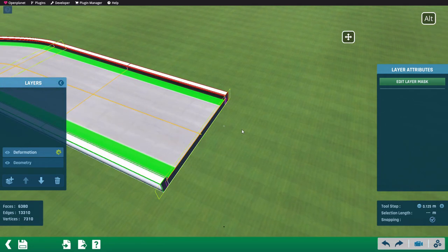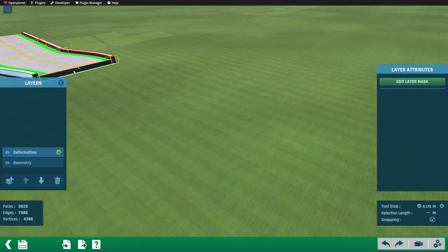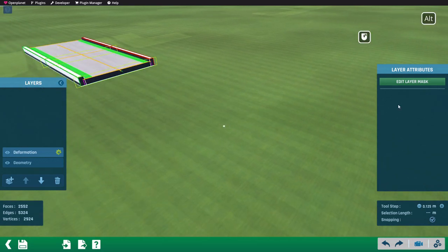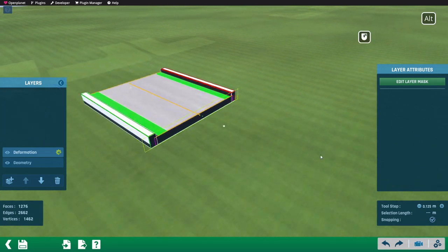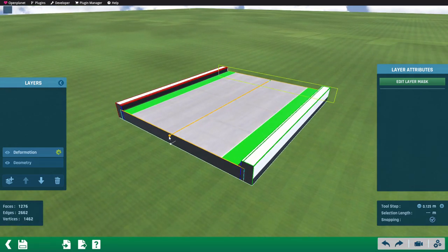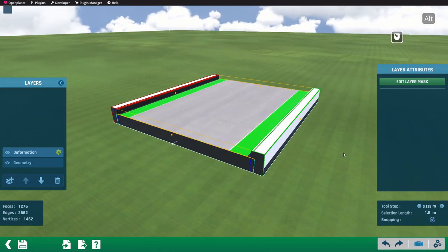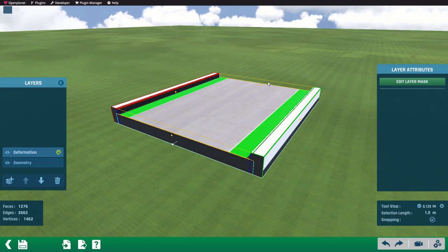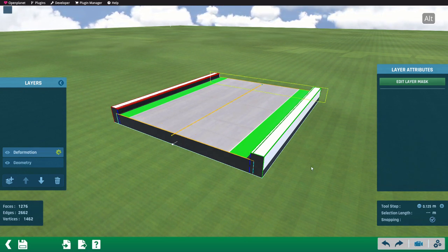Number 1. Selecting the origin of the spline. This option is only applicable when there is only one control frame. The origin of the spline defines where it starts. To select the origin, click on the orange dot representing the current origin. You'll enter origin selection mode, where 4 clickable orange dots, one on each side of the geometry, will appear. Choose the origin by clicking on one of these orange dots.